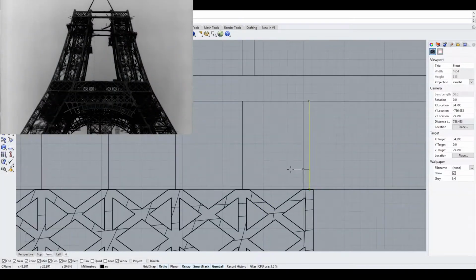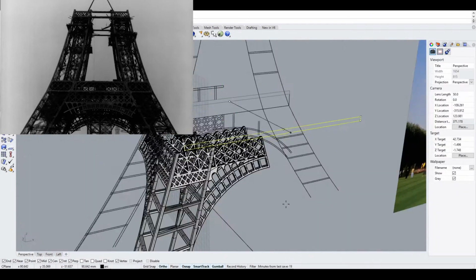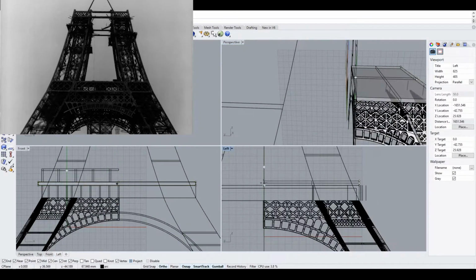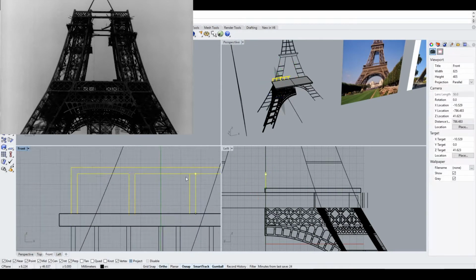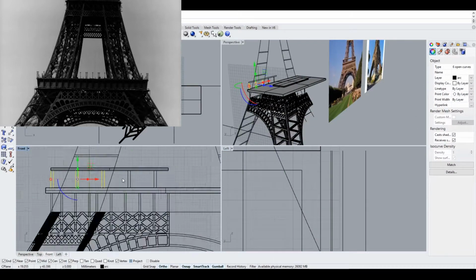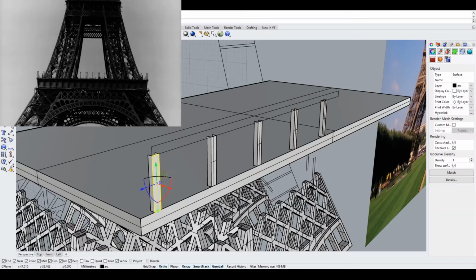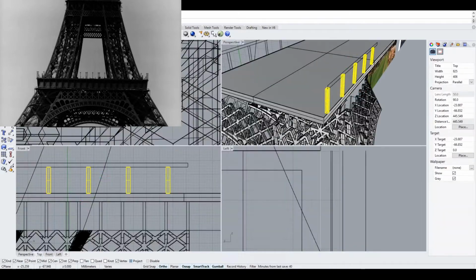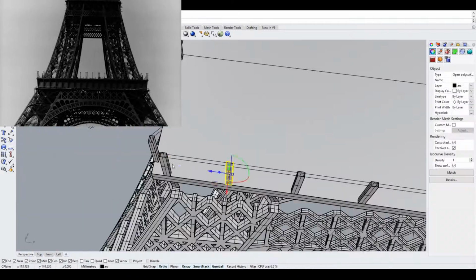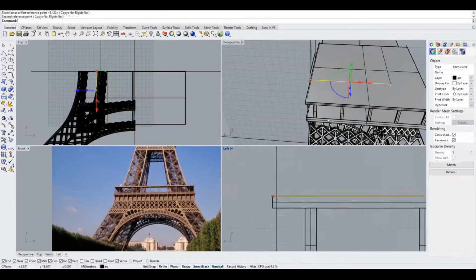Sandboxes and hydraulic jacks, replaced after use by permanent wedges, allowed the metal girders to be positioned to an accuracy of 1 millimeter. On December 7, 1887, the joining of the major girders up to the first level was completed. The pieces were hauled up by steam cranes, which themselves climbed up the tower as they went along using the runners to be used for the tower's lift.